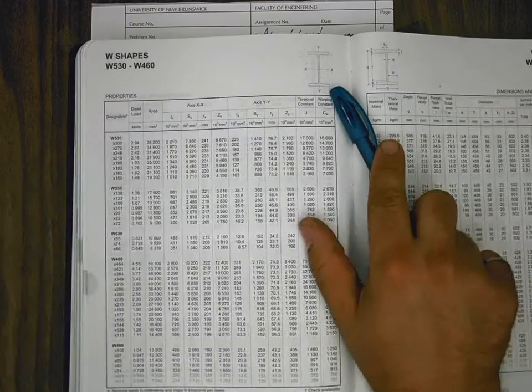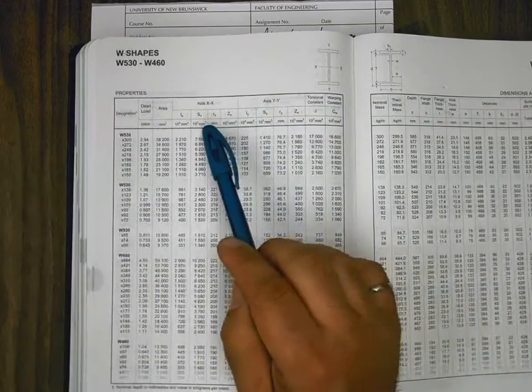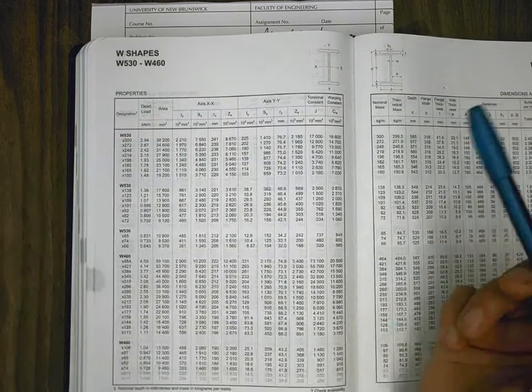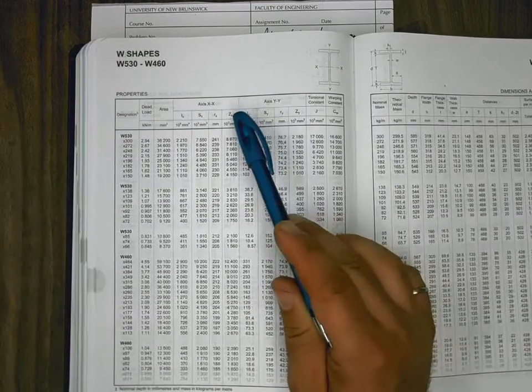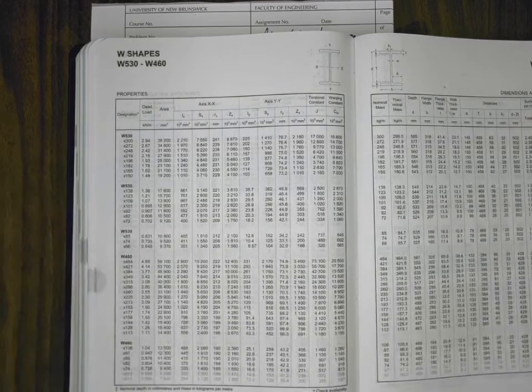Now, if we look at the steel handbook, we would see properties of shapes, in this case W shapes, and we could go to the handbook and pick off a moment of inertia and values called section modulus: the elastic section modulus and the plastic section modulus. The magnitude of the section modulus allows us to directly calculate moment. The elastic one allows us to calculate the yield moment, whereas the plastic one allows us to calculate the ultimate moment of the section.